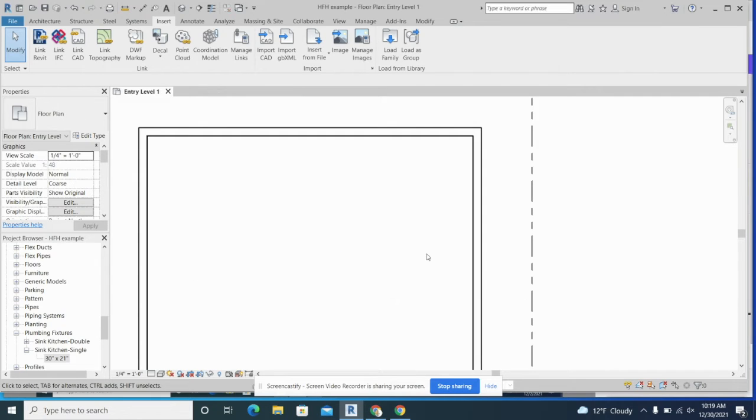here. Okay, so here I am in my little example house, and here is going to be the corner where the kitchen is going to go. So you saw what I had before, and I'm going to recreate that a little bit here. One thing when you are laying out your kitchen, if you have any corner cabinets, you always want to start with those because you can't really adjust the size at all. They come in that standard size.